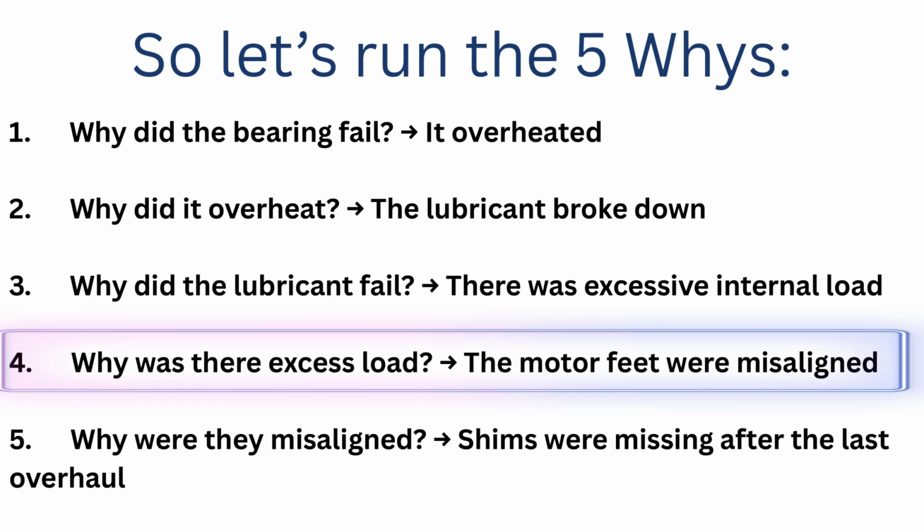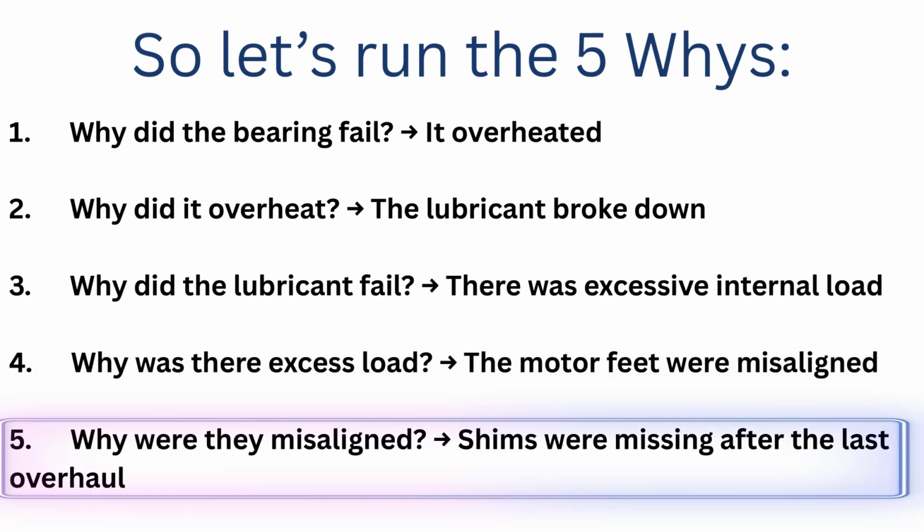Maybe there was a soft foot in the motor, or maybe there is a misalignment, right? Again you will ask why is this misaligned? There is a possibility that the machine recently underwent maintenance, and during the maintenance maybe the technicians didn't do the proper alignment, or maybe they didn't use the proper shims under the motor foot. So that can be the root cause. So here what is the root cause? That improper alignment, or you can say the soft foot in the assembly.